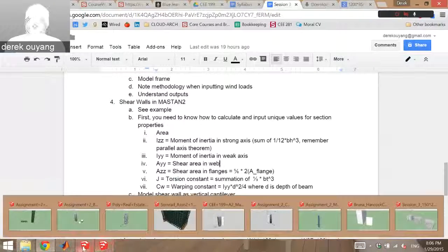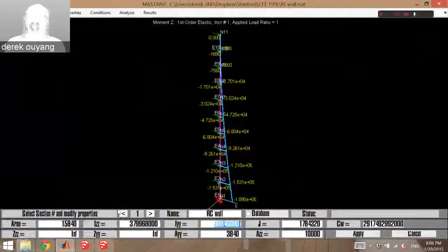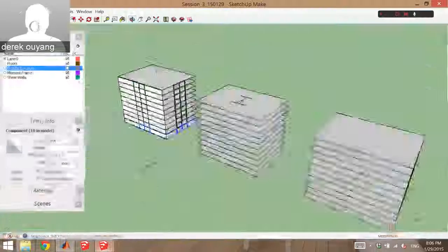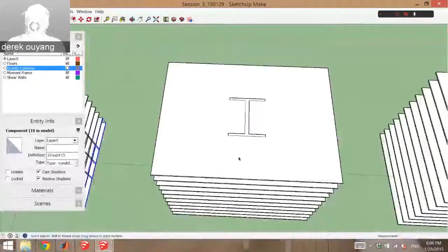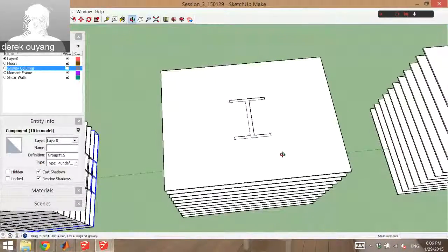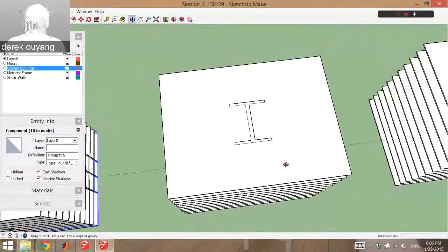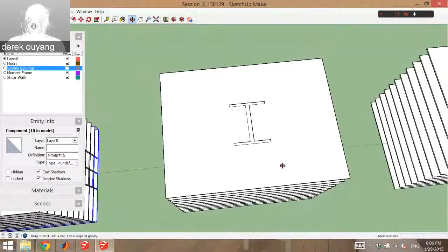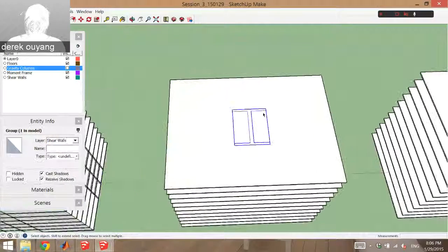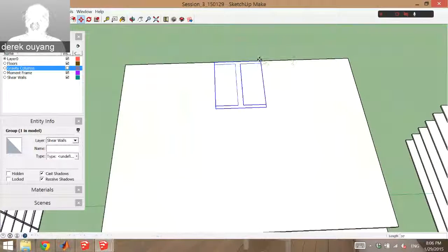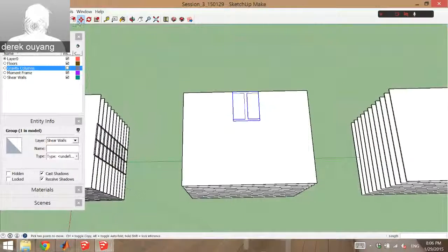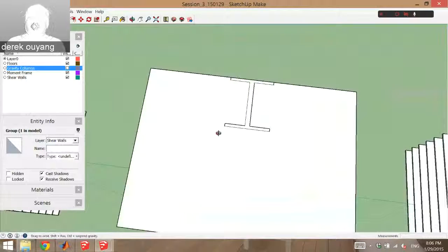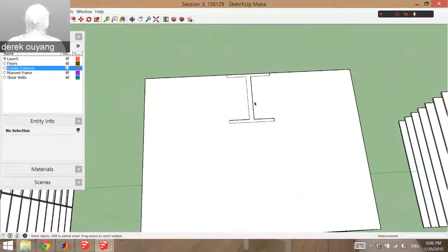Okay. Let me just quickly show you what you might have to consider if the building is different. This is a simple version because the shear wall is right in the center, so you can say that the actual force it feels is right in the center, either here or here, right? And so that just means it translates into a point force on each floor. But what if that concrete shear wall, for an architectural reason, was back here? Let's generalize this to: the architect puts your lateral system in a really strange place. So technically, this building is still experiencing the exact same force.